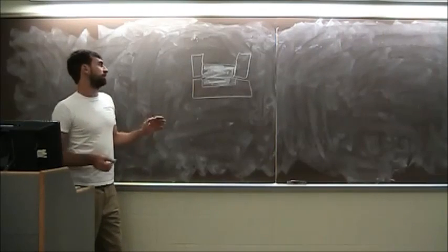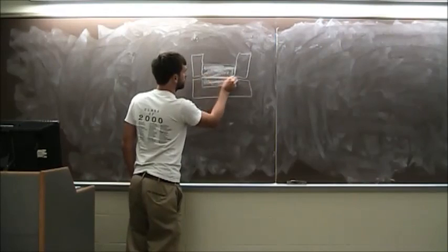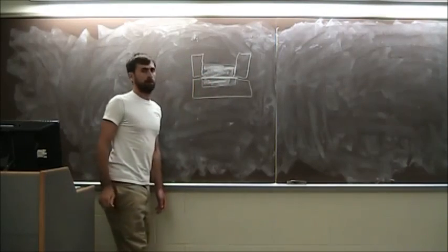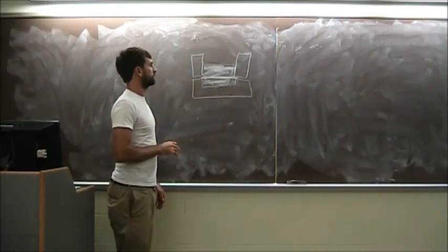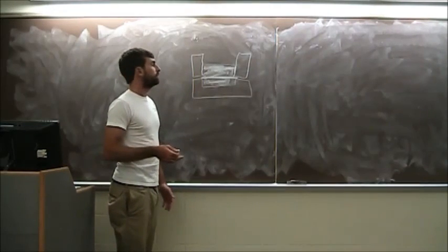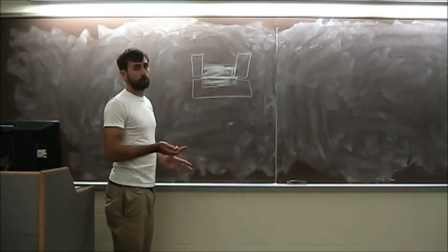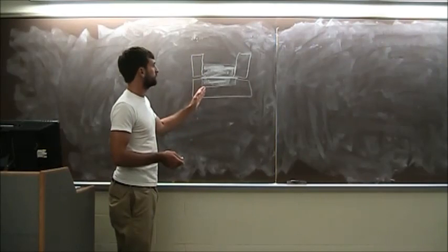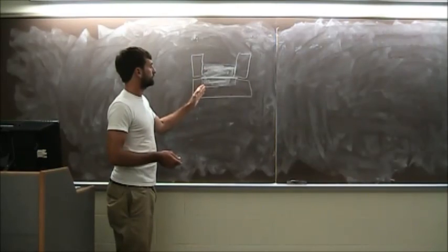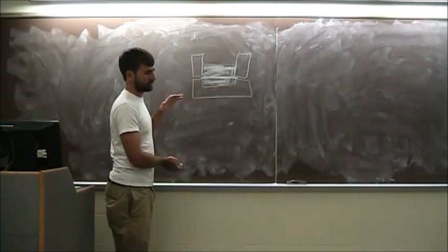And also, one of the major disadvantages is you're forcing failure to happen through a horizontal plane, which may not be the plane that failure would occur in if you were to see it in the field. There's a lot of things that determine where that failure plane is. There could be a weak slip plane. These might not have the same properties horizontally and vertically or in all directions.